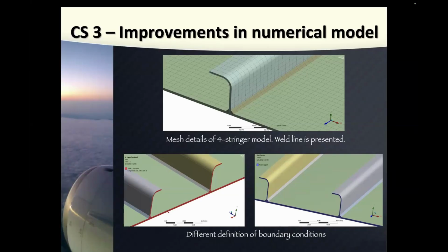But when you check the recorded values from the machine, you see that the force is varying. Sometimes it's 18,000, sometimes it's 16,000, because over time the resistance of the material decreases. The machine can adjust to that, but not 100% correctly. So these guys used the maximum and minimum values as if they were fixed, not changing over time. I checked their results. The Paris coefficients they got were calculated correctly, but the input value was not good.